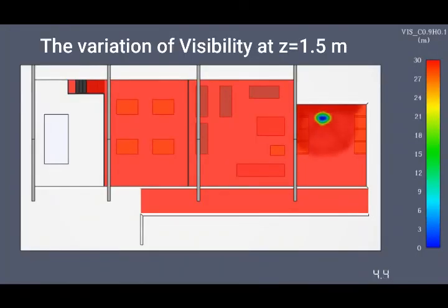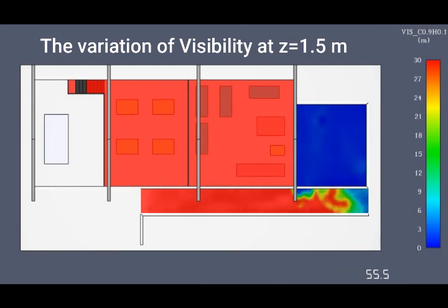The smoke visibility calculates the distance a light sign can be seen in a smoke-filled environment. According to the results, the smoke visibility in the welding room will be almost zero at the 20th second. Therefore, occupants should evacuate from the welding room at least within the 16th second.